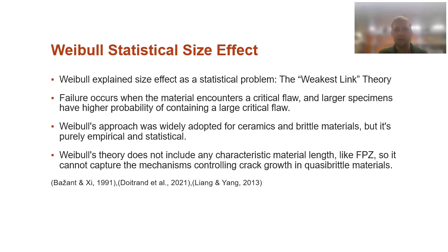And for a long time, this was it. This was the method, and people really agreed on it. It does explain some things very well. It still does explain brittle materials, and we'll see that Bazant acknowledges it and accepts that it will apply for some types of size effect. So don't count it out. Just know that we might be trying to work against the grain here in a little bit, mostly because it doesn't include some of the fracture mechanics mechanisms like energy. It doesn't account for those.